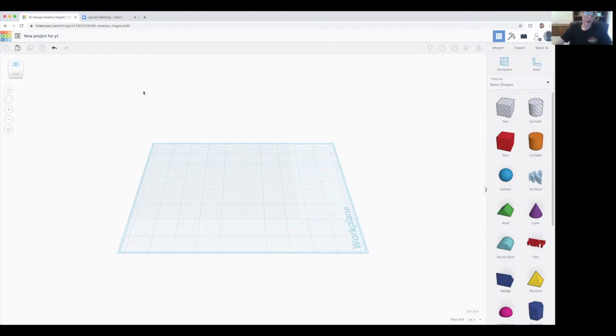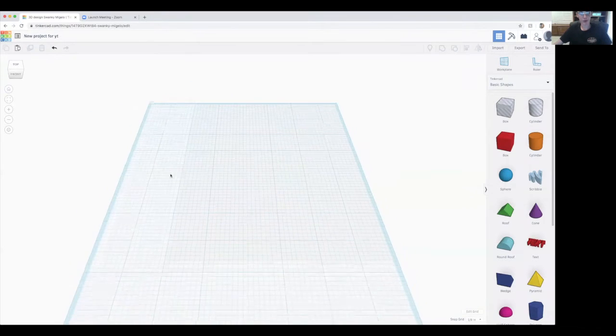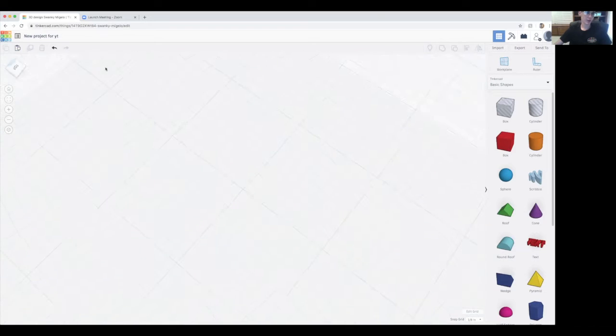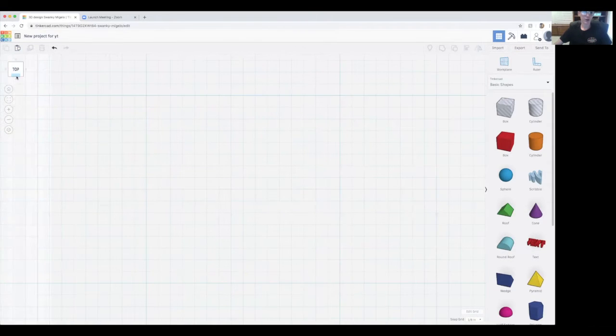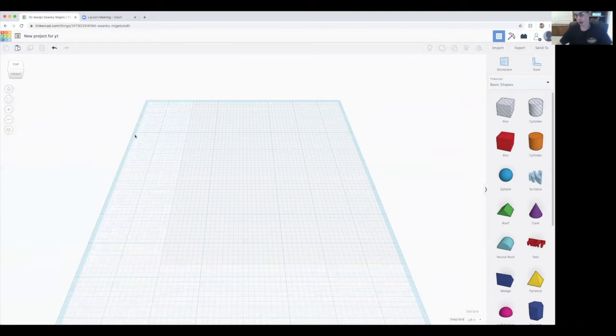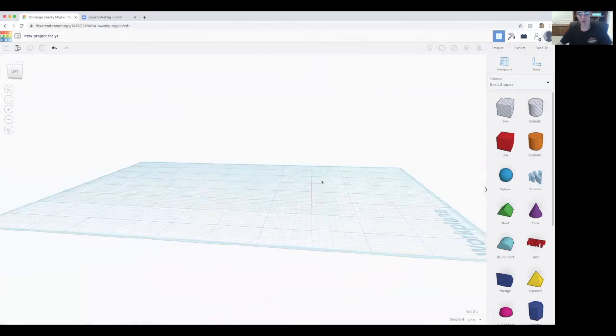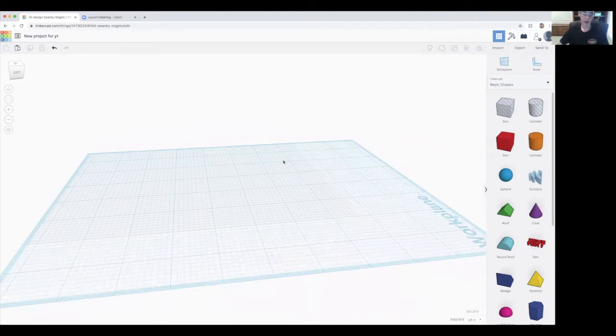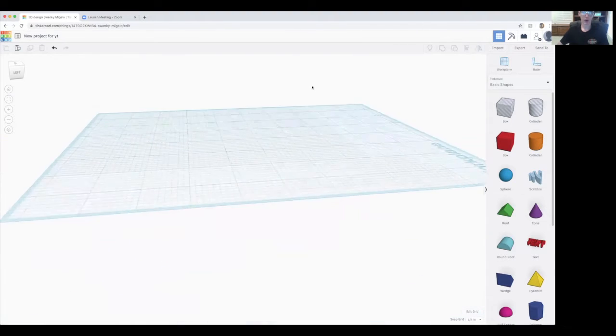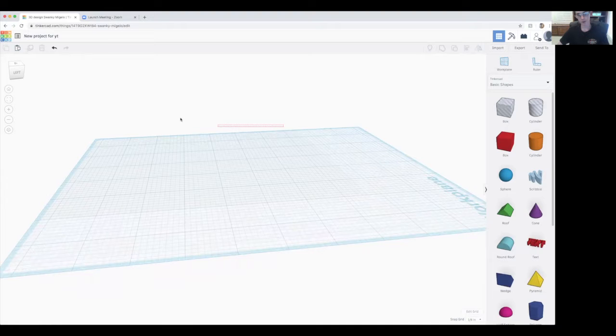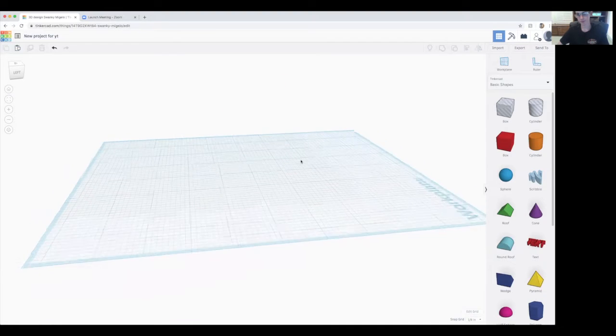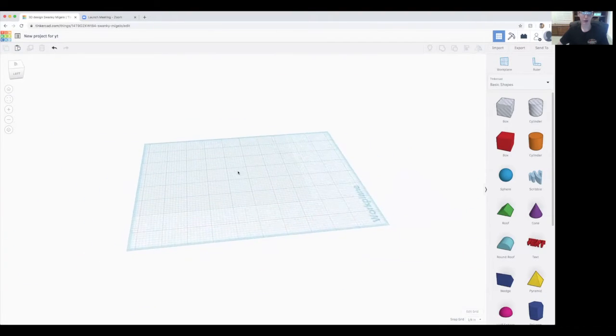I have set up a new project, so you can rename it over here. And I can do things over here like that button. That's the home button, so it resets it to the home position. This up here, you can use it to change how you're viewing the angle. So I'm stuck on the top, so I just press home. On a mouse, if you press the right button, you can look around like that. If you press the right button and shift, you can move around and it looks kind of cool. Left button selects stuff. Scroll does in and out.